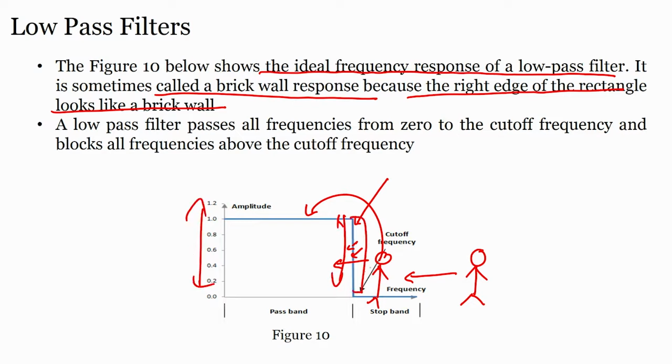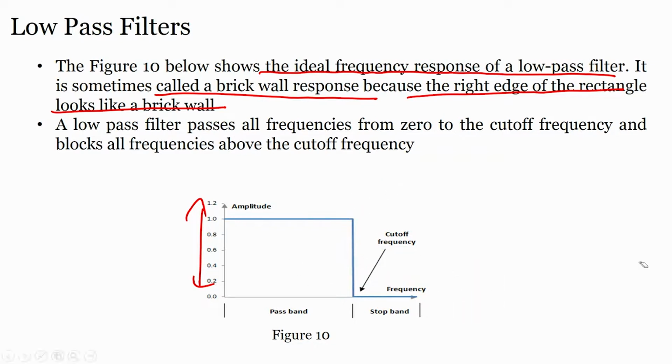So, this is like a brick wall, I will hit myself against the brick. There is only one way that we can remove this brick wall, and that is by changing the filter, by changing the cutoff frequency. If I have to move further inside, I will design a filter with a cutoff frequency this much, and I can run till here, or another way, I can stop at this point.